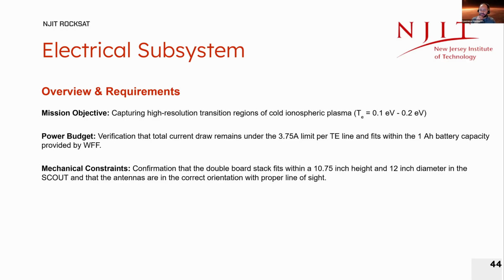Okay, so I'll probably put this in as a suggestion then, because I'm trying to allocate everyone their own portion of the spectrum. There are just 3 other teams using 2.4 gigahertz, so it's not as bad as LoRa currently. If you were to use channel 25, Virginia Tech could use 26. You would use 25, and Alabama would basically stay where they are. They're between 2412 and 2452, so they're a little bit wider. They're 40 megahertz. It's very data hungry.